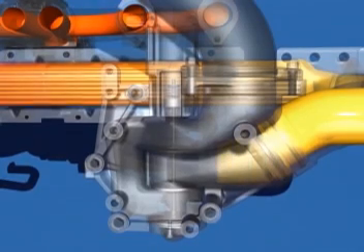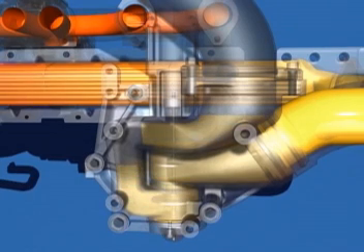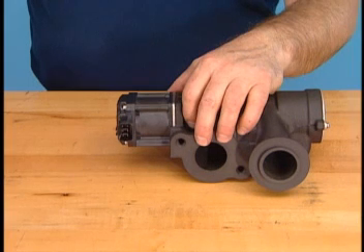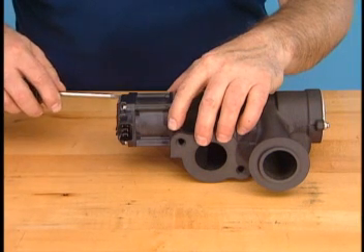The outwardly opening poppet valve opens into the exhaust manifold and is controlled by a high-speed electric motor. The actuator on the valve signals the ECM the actual position of the EGR valve. The ECM constantly adjusts the valve lift through the use of the motor to produce the necessary gas flow. The EGR actuator is serviceable.